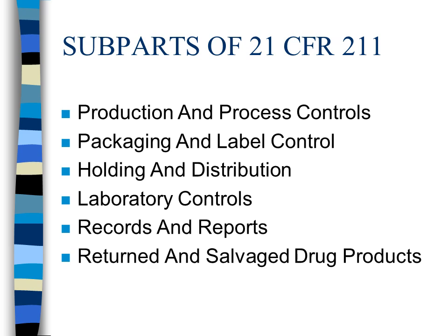Complete the complaint form as accurately and as completely as you possibly can, and make sure that the cylinder is designated as a complaint cylinder so that when you return to the branch, you can get a QCU member, you can show them the cylinder, they can quarantine the cylinder, and you can hand them the customer complaint form for their investigation.